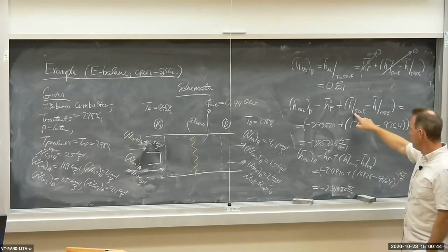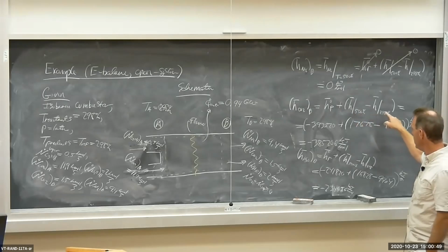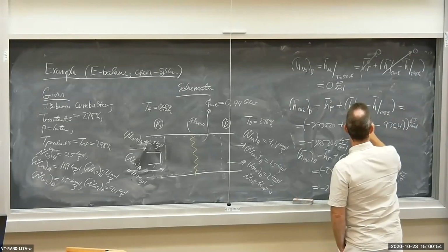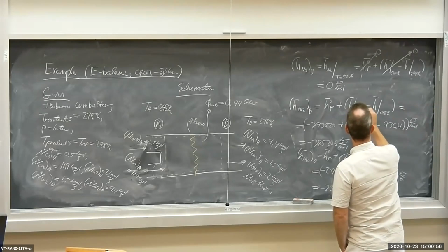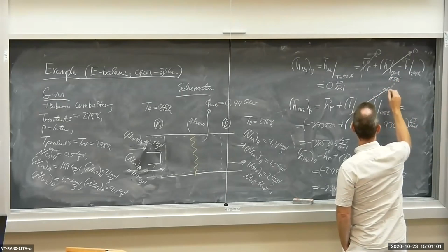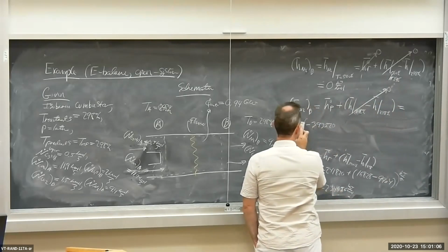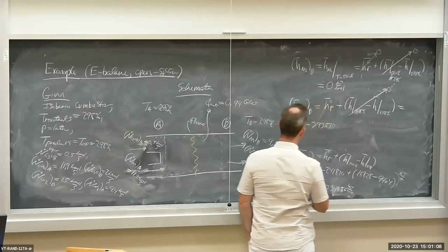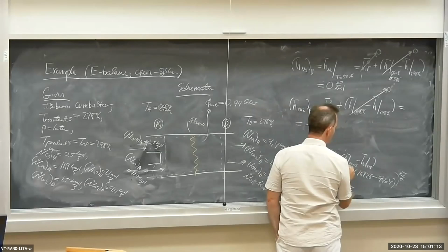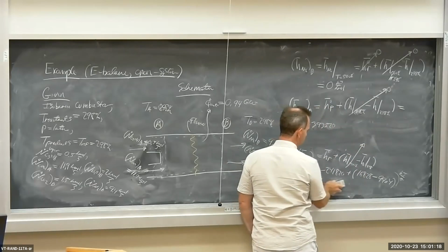On the CO2, the delta H term is now H at 298, the reference temperature, minus H at 298, the reference temperature. So the delta H term is now 0, and I can get rid of this, and all I have is the enthalpy of formation. Same thing for the delta H term on the water vapor at the outlet.